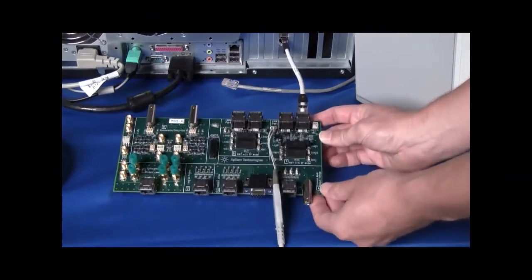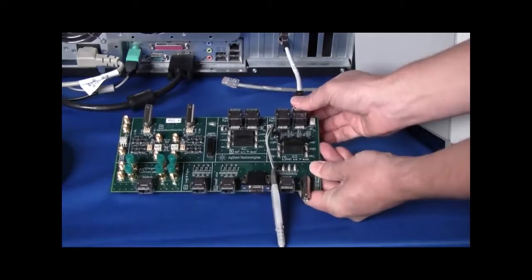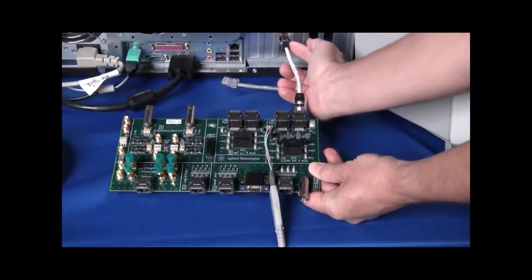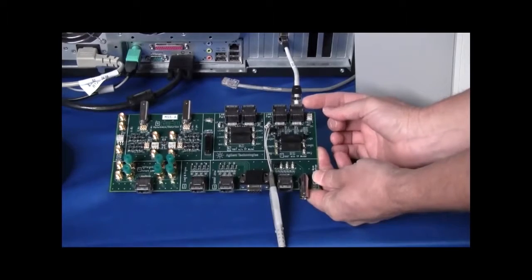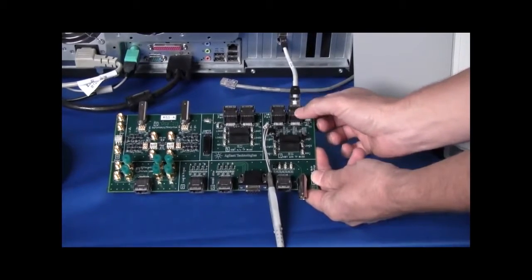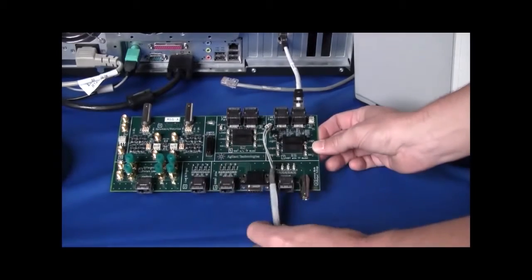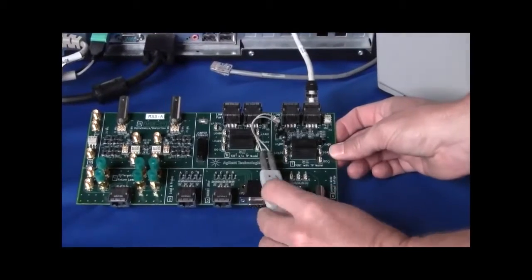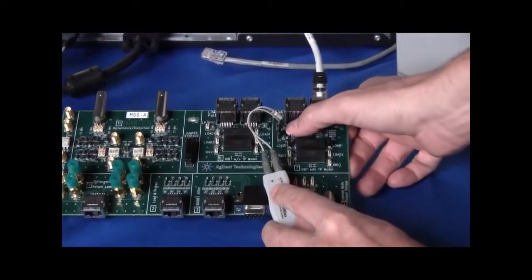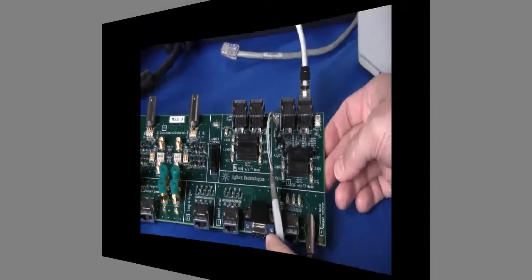This is our Agilent test fixture. This comes with the Agilent Ethernet test application. We have our DUT on this side connected to our Ethernet cable, which is connected to the DUT side of this Ethernet connection. Also, we have the probe connected to our 9000 oscilloscope, and we want to make sure our polarity is correct on the probe versus our test point. And that's our setup that we're starting with.